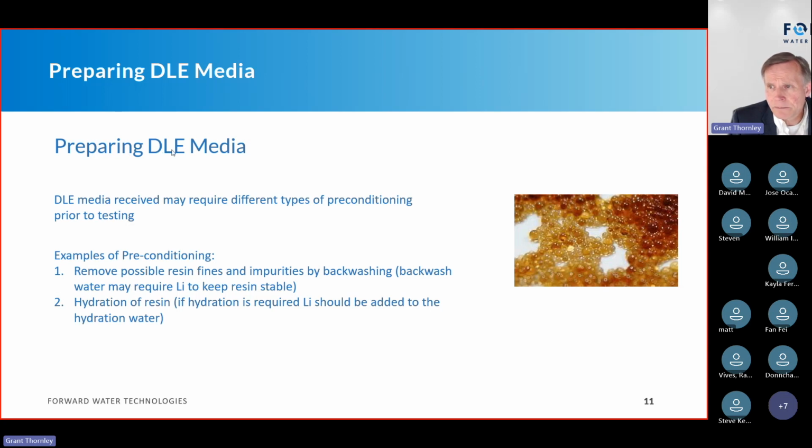Preparing DLE media. This really touches on the fact that sometimes the DLE media provider is going to say, look, I will send you media and you do it, or the DLE media provider is going to do it at their facility. Either way, if you're going to be doing the resin testing at your facility, or you're going to hire a third party to do it, you really need to know what the condition of the DLE media is before you do your testing, and whether you have to do some preconditioning.